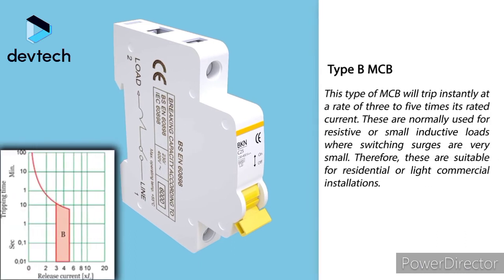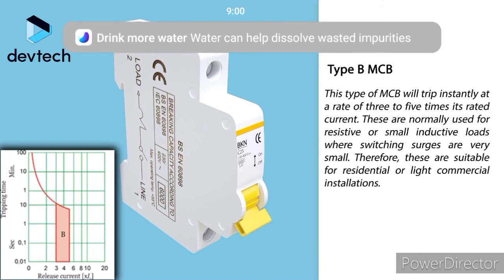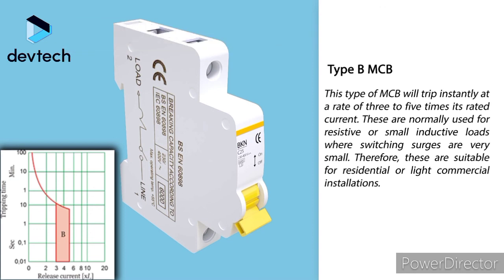Type B of miniature circuit breaker. This type will trip instantly at 3 to 5 times its rated current. These are normally used for resistive or small inductive loads where switching surges are very small. Therefore, these are suitable for residential or light commercial installations.